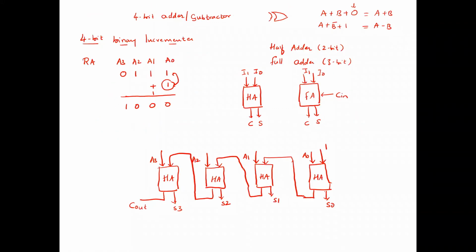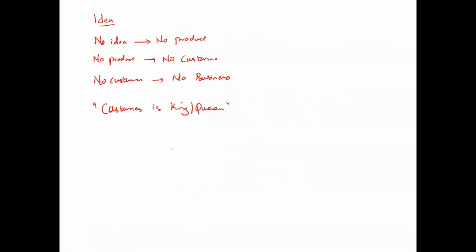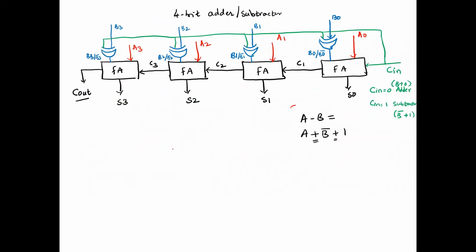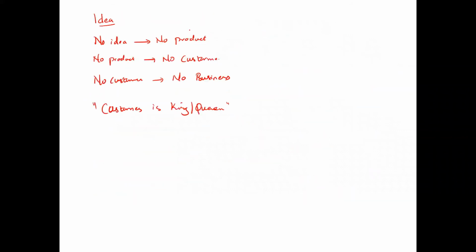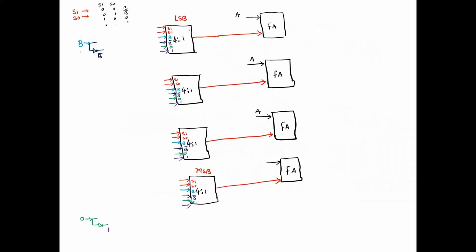So how have we done here? A0, A1, A2, A3, and the full adders we have also drawn, right? Here, A0, B0, full adder 1, A1, B1, full adder, A2, B2, full adder. So what kind of arithmetic circuit are we going to draw here? It is 4-bit, right? So we are designing a 4-bit ALU.